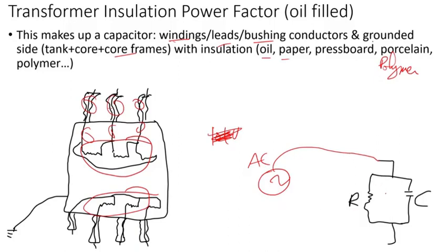Basically, if you take the windings, then the insulation, when you energize the windings, they are isolated from ground. They are not connected to anything, not completely in circuit. So if everything's perfect, this resistance here should not exist. It's just a capacitor, because the only thing that completes the circuit is the capacitance from what you're energizing to ground.